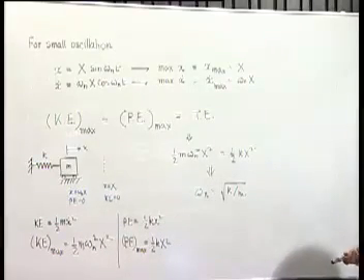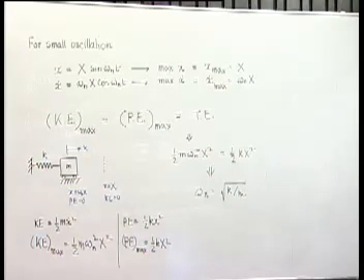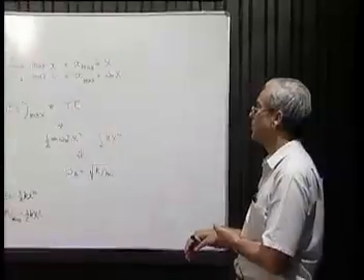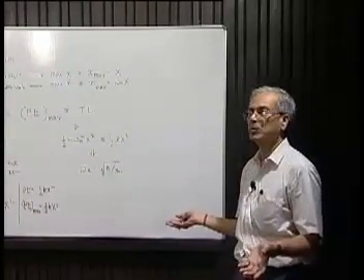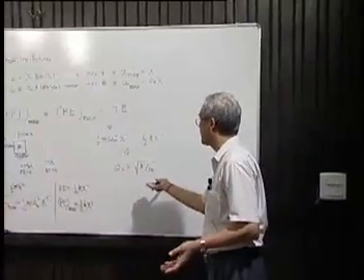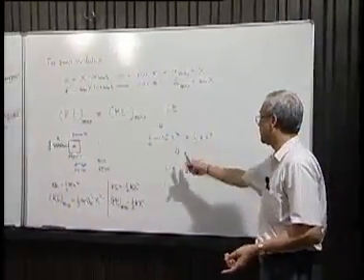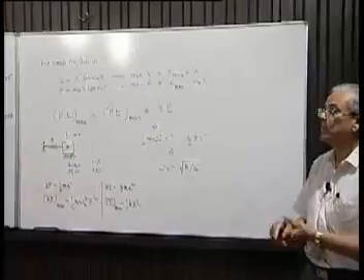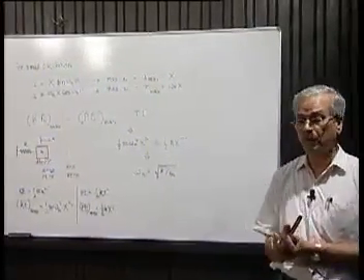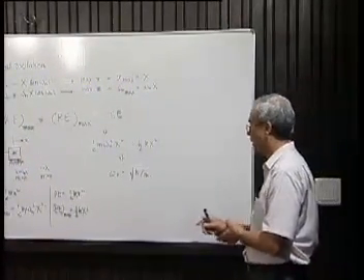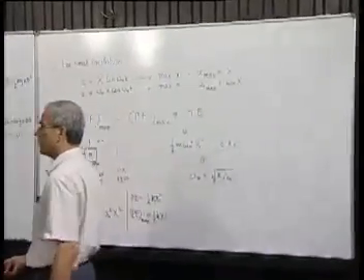So this is another angle of the whole thing. We can use this concept: we find the maximum kinetic energy and the maximum potential energy, treating the potential energy at the equilibrium position to be 0, and equate them. Thus we get an algebraic equation, not a differential equation which we have to solve, whereas on the other hand, with the equation of motion we get a differential equation, and we have to solve it. So this, of course, you may think is a very trivial problem.